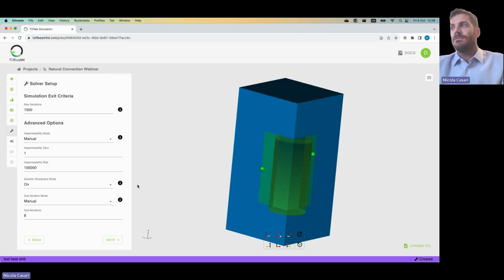And we found that for tightly coupled problems such as natural convection, and with tightly coupled, I mean that the temperature solution actually affects the pressure and the velocity because they are linked with the Boussinesq approach, we need to iterate more and more between the two systems in order to achieve better convergence.